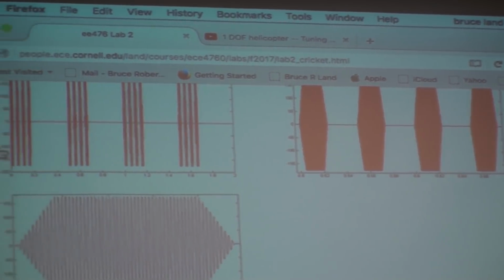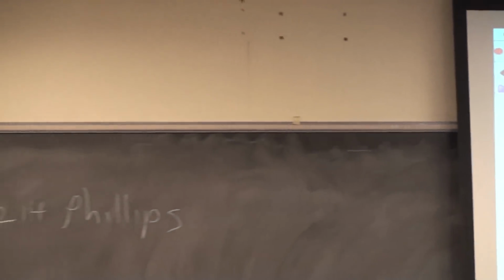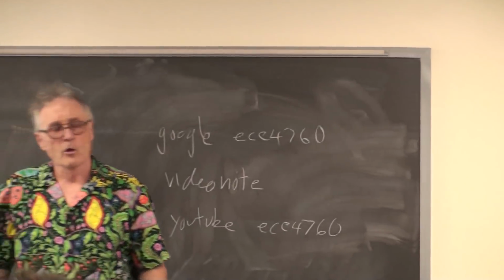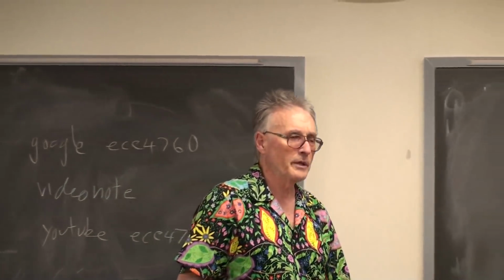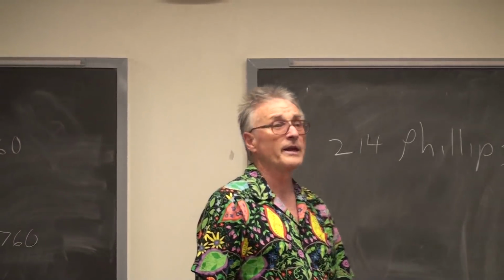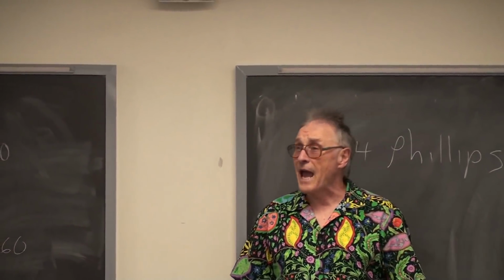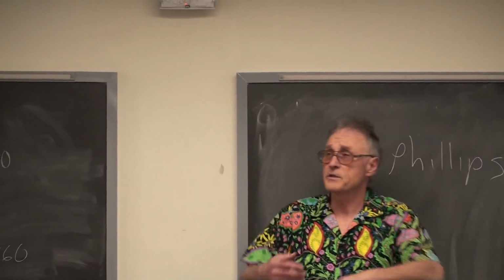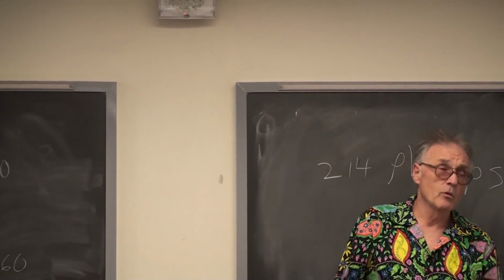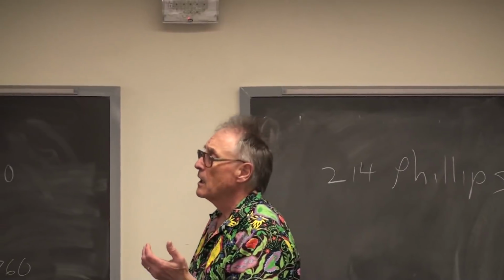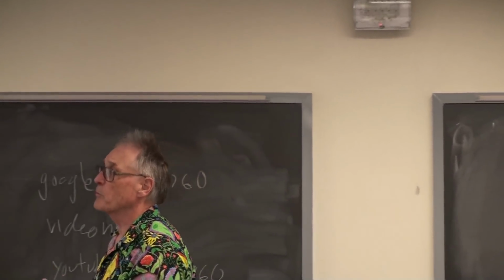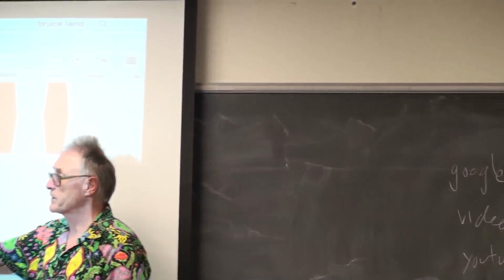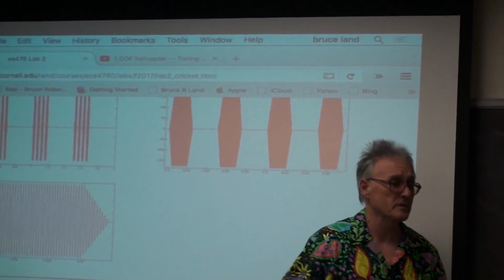So the theory here is direct digital synthesis. How do you build a sine wave on a cheap little computer that you can output at 44 kilohertz for audio quality? The peripherals we'll be using are serial peripheral interface to drive the DAC, that is a serializer. SPI is a high-speed serializer for outputting serial data, and a timer which will do the high-speed synthesis. In other words, it will produce 22 microsecond precision intervals for doing the sampling for the direct digital synthesis.